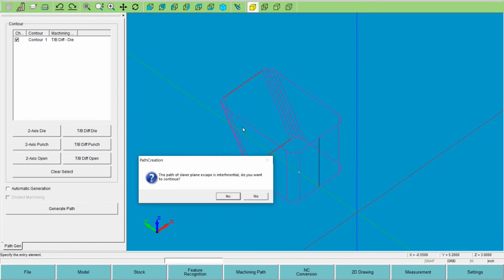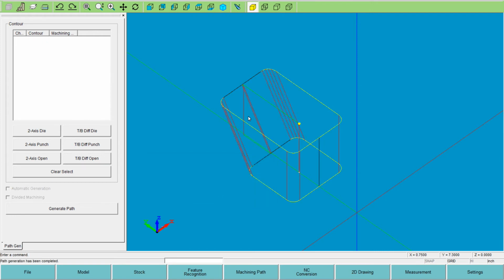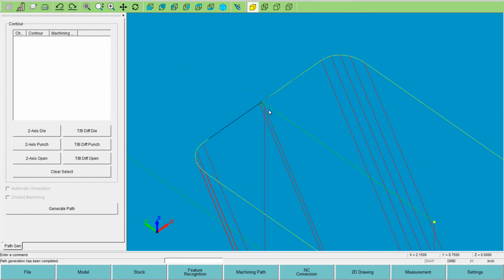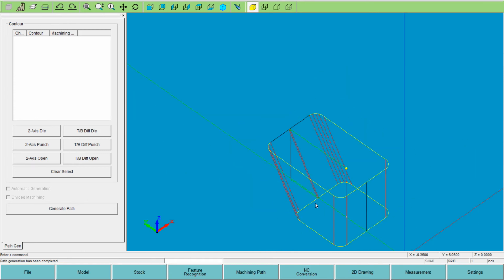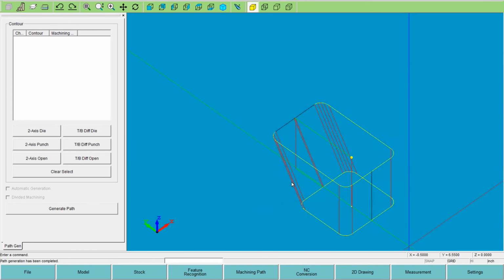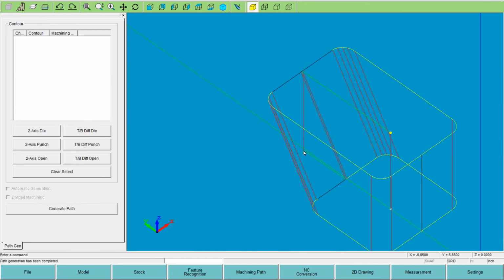Because it's now at the top. The table of programs up at the top, it backs off 100, and you're going to see what happens. I'm going to just say yes. See the little move here? So that's the top was the reference, and it did the 100,000s, but while it's straightening up, it's got to cut the bottom, and that's going to gouge into the piece. So it gives you an alarm you're doing that because we didn't give it a big enough release move.